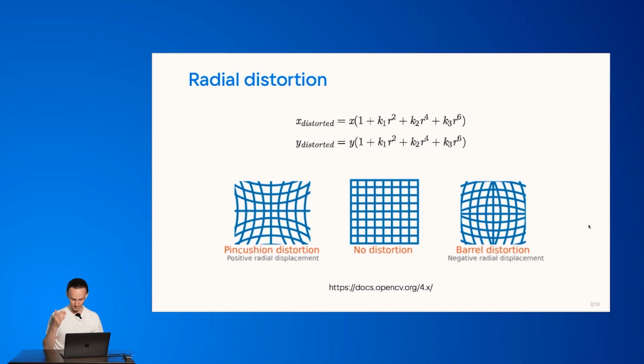We have to calibrate the optical system or the camera of each robot individually, because those lenses are slightly different and the cameras themselves are mounted in the head of the robot slightly differently. So if we change the lens, if we even adjust it, even just randomly, or if the robot has fallen onto the ground, we will have to readjust the optical system by calibrating it once more. This whole procedure is about getting those parameters.